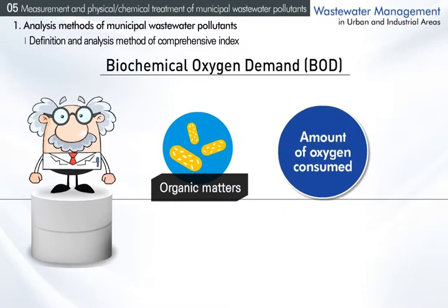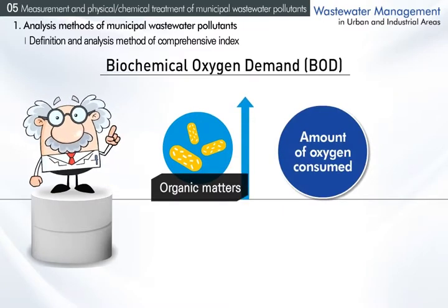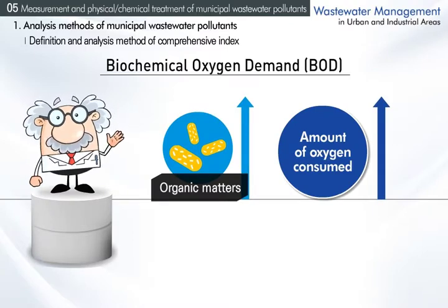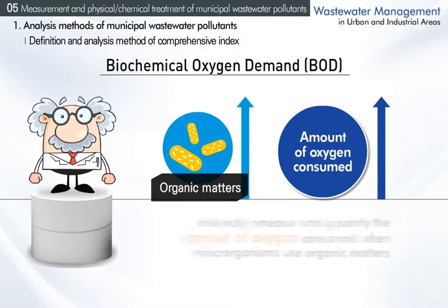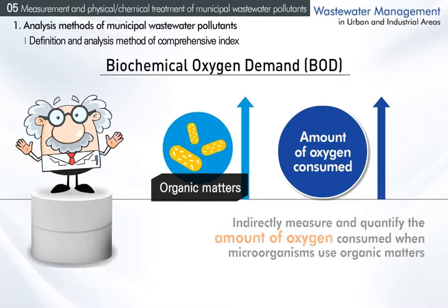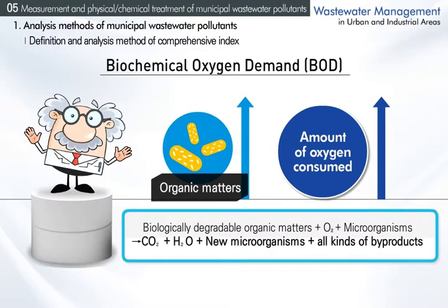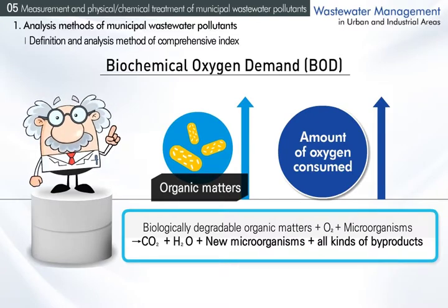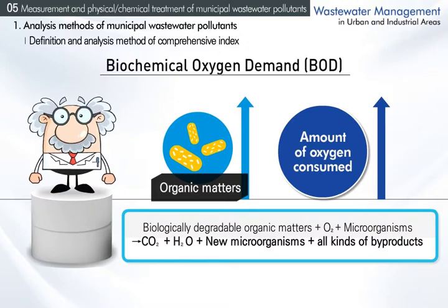Also, the more organic matter there is in wastewater, the more oxygen is consumed while microorganisms breathe. Thus, BOD can indirectly measure and quantify the amount of oxygen consumed when microorganisms use wastewater organic matters. Such a BOD analysis method can only measure the amount of biologically degradable organic matters in wastewater. Its concept is shown on the screen.